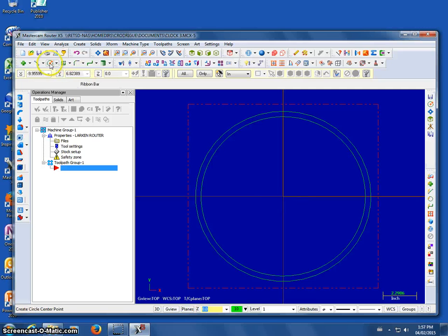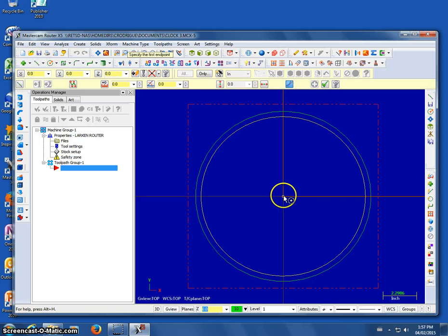So the nice thing is I can go over here, create a line, click on the create line endpoint tool, then go to the origin, it snaps again, and I draw a line. This is just a guideline, we're getting rid of these after, so just go past both circles and click. Now I've got that line there. You'll notice it's 8 inches long or so and has 32 degrees of angle to it. But I don't want 32, I want 30. So I go over there and type that in and hit apply.